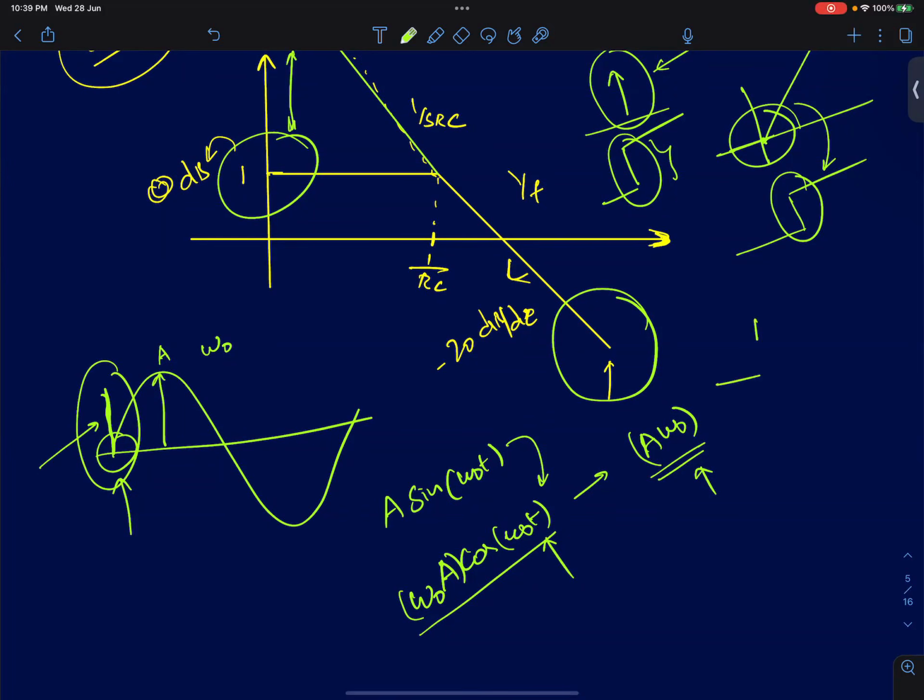When you have a sudden change, the system that you feed this input to will interpret it, at the instant you apply it, as a sinusoid of infinite frequency. So to predict the behavior of the system, what is it going to produce as an output? You have to look at the frequency response and see what the behavior is at omega equal to infinity, right?